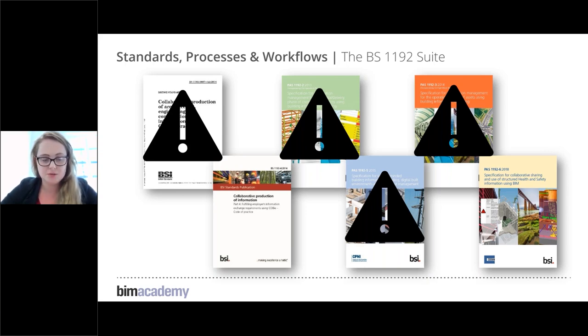You'll notice that two here don't have a big angry triangle on them, and that is part 4, which looks at all things COBie, so construction, operation, building, information exchange, and how we ultimately deliver our non-geometric data, and part 6, which is looking at the use of health and safety information using BIM. So part 1, which is working collaboratively in a common data environment, that's now been superseded by ISO 19650, as has part 2, which is BIM in the delivery phase, part 3, which is BIM in the asset management phase, and part 5, which is BIM and the security of information.